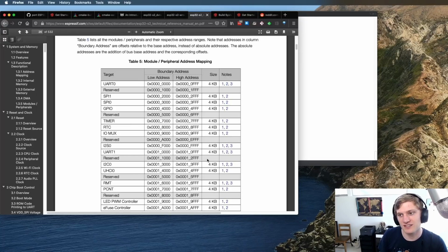And so what he let me know, and I've learned from that, was that on the M7s at least, you have to be pretty particular about telling it, oh yeah, your memory space is 8 megabytes, but the flash you're talking to is only 4. So make sure that those other 4 are marked as invalid and not able to actually fetch. And this will probably, I don't know exactly where it is, but the ESP32, because it uses external memories, that's another thing we still have to be aware of.